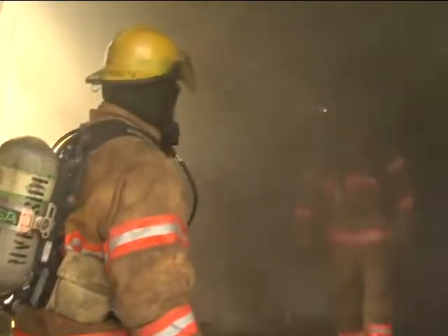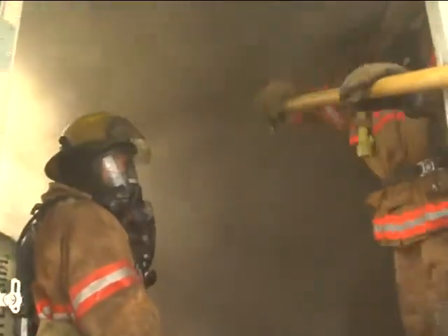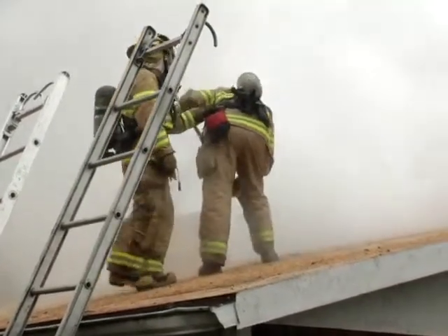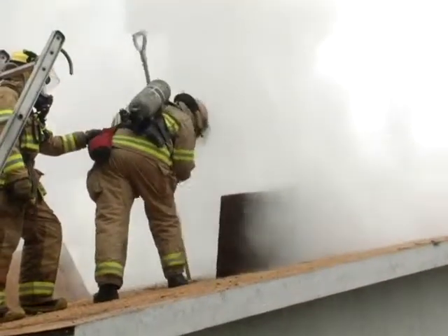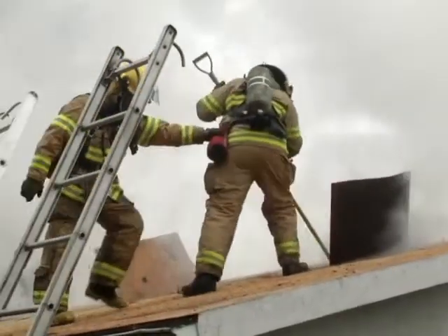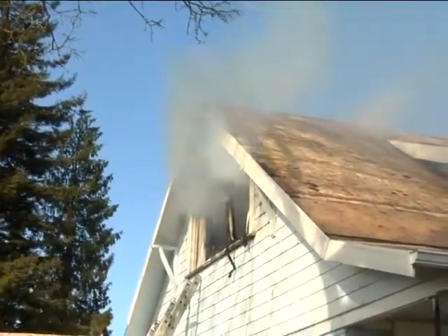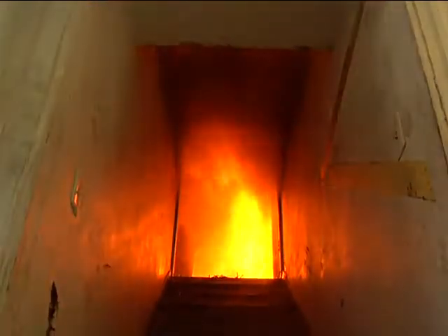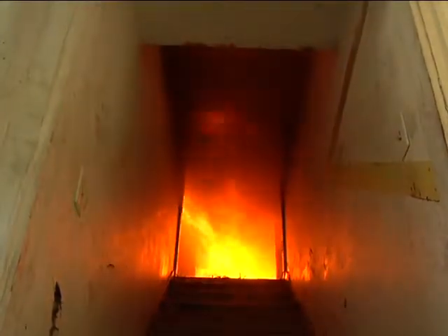Vertical ventilation is the systematic removal of the byproducts of combustion, smoke, heat, gases, and sometimes flames through vertical channels in a structure fire. Most often, vertical ventilation means creating openings to allow these byproducts to exit from the top of the structure, the roof. Vertical ventilation can also involve moving the products of combustion from basements or multi-story structures through stairwells and other vertical openings. Vertical ventilation works because convection causes heat, smoke, and fire gases to rise to the highest point until trapped by the ceiling or roof.